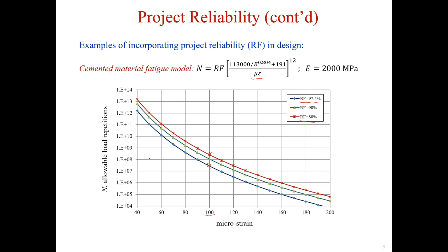And you can see in this graph here the significant effect the reliability factor can have on the predicted life for a given strain. So the choice of reliability level for the project has a significant effect on the life that you calculate.